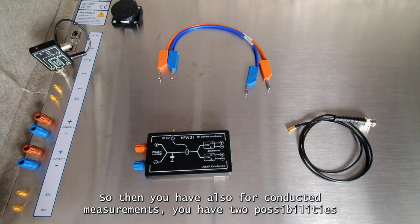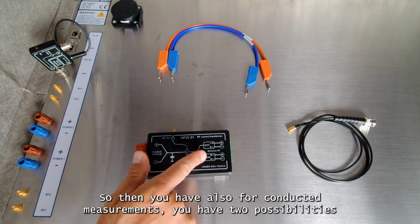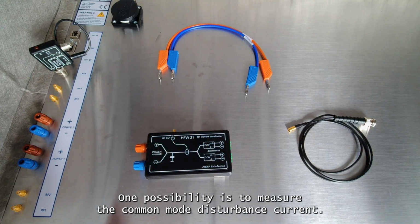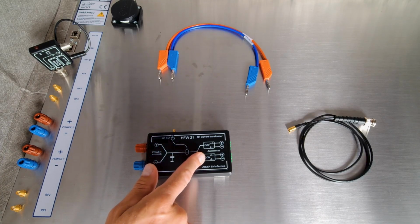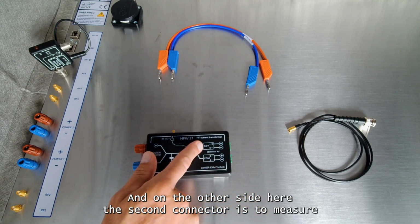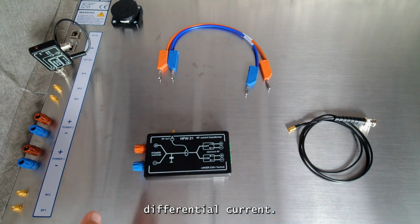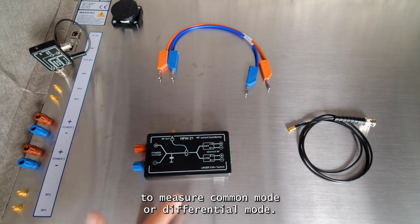So then you have also, for conducted measurements, two possibilities here. One possibility is to measure the common mode disturbance current, and on the other side here, the second connector is to measure differential currents. Later I will explain why it is sometimes important to measure common mode or differential mode.